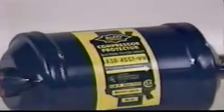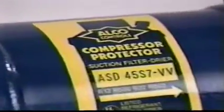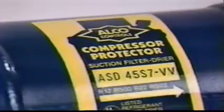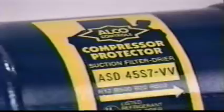It is the filter dryer that must be used to do the cleanup, and it is the filter dryer that's installed in most new systems to start them clean and keep them clean. Whether the filter dryers are installed to clean up a system after a compressor burnout, or are installed as insurance to keep a system running cleanly and smoothly, they are a tool for which there is no substitute.